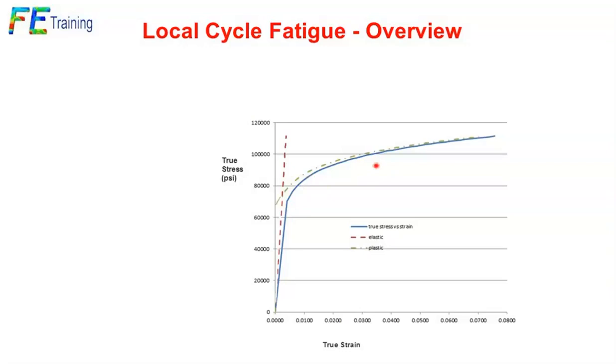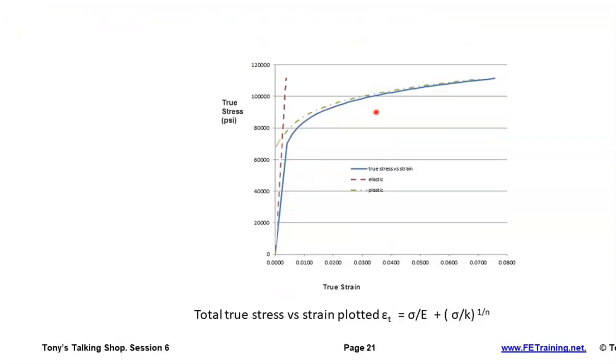We've got macro level stresses, a simple stress definition. Somewhere locally in our hotspot, we've got this going on. And this is what we assume. Now we've got to go from our elastic response and transition to our plastic response locally. We're not going to run a nonlinear elastic analysis, so we've got to have some way of fitting that through. And that's thanks to Neuber.